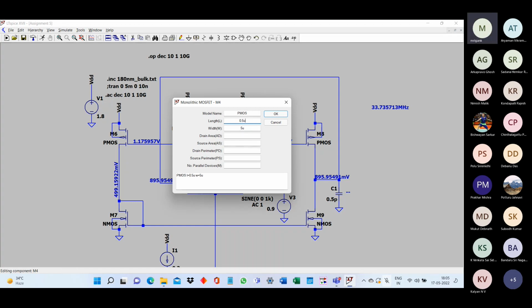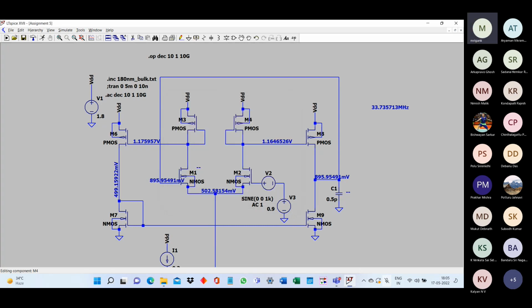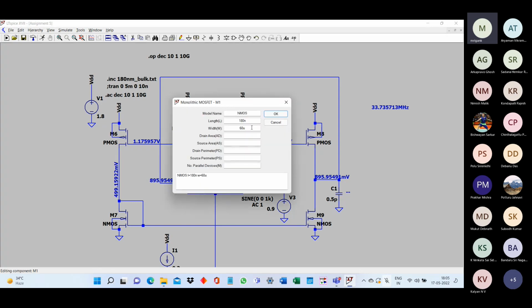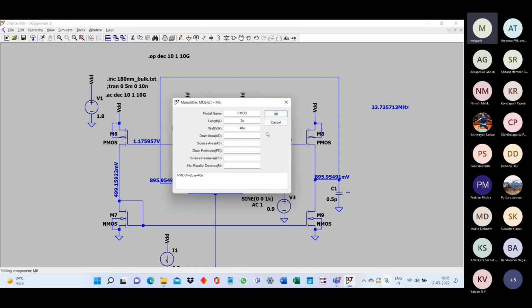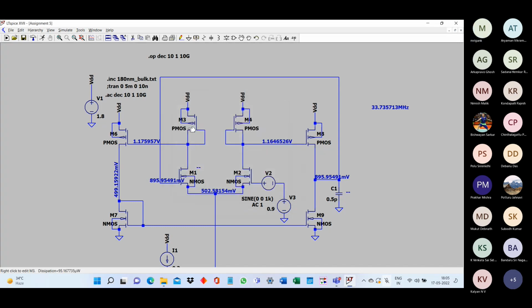So the ratio we should track, because ultimately we have assumed that whatever is the small signal current, gm VGS, produced by the first stage input devices, the same small signal current is routed through the second stage. But if your M3 M6 mirror ratio is smaller, M6 W by L is much smaller than M3, then that small signal current going through M6 will also reduce.